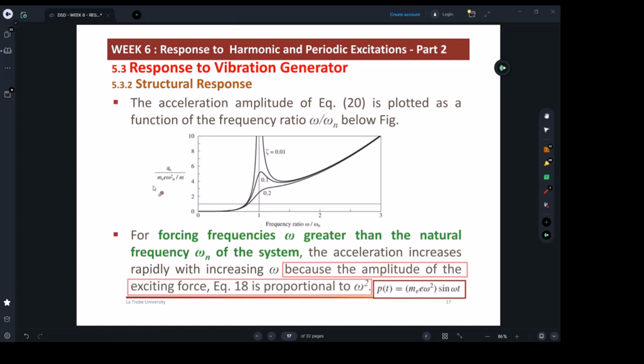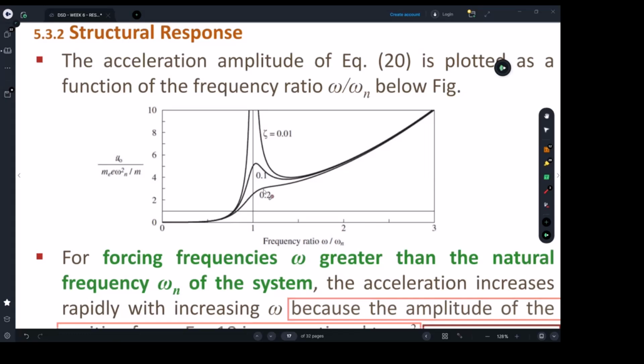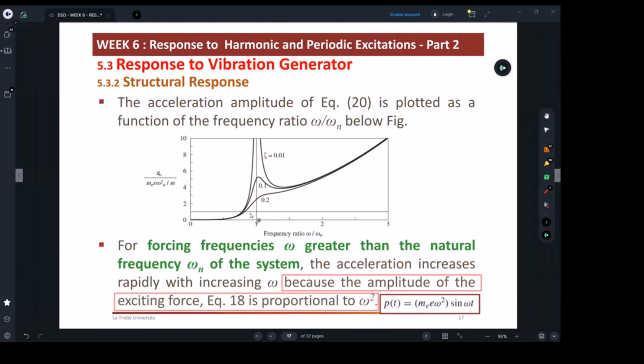You're always going to apply frequencies and mass which will be way below what would reasonably break a building. So don't expect to take your machine and keep throwing masses in the bucket, or use special weights. You're going to do some preliminary hand calculations that will tell you what level is within a safe range. Again, that will depend on the stiffness, etc.